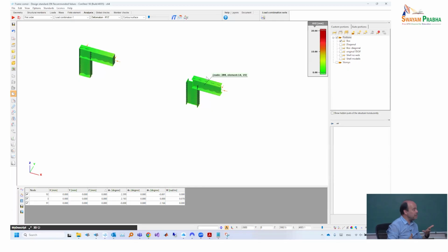We believe that we know more, and when the engineer selects this topology, basically it gives additional information to the beam element-based model, which is not stored and not included in the beam element, about the way the deformation should be transferred. And we solve this transfer not by the beam elements themselves, but by an additional constraint transmitting the deformations the way we want.